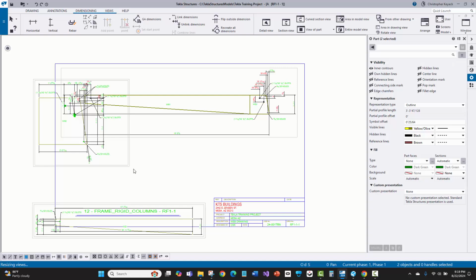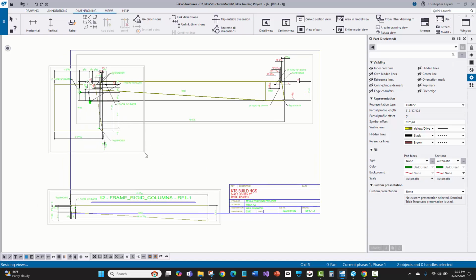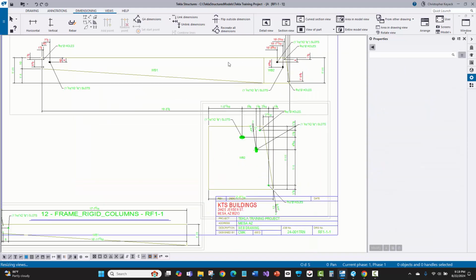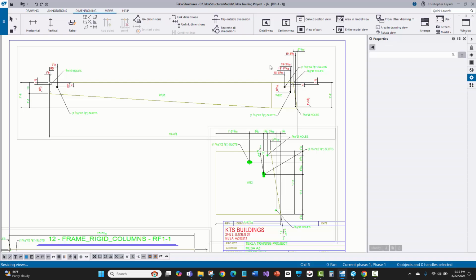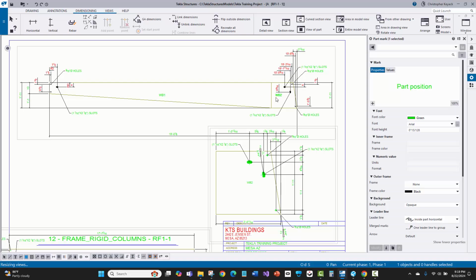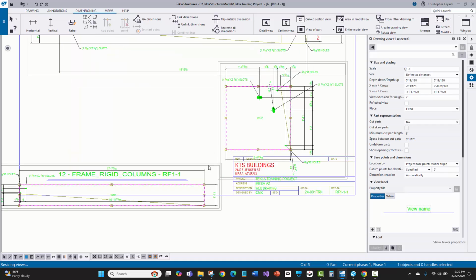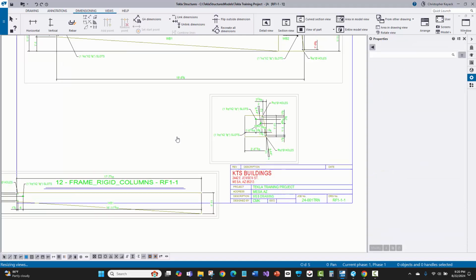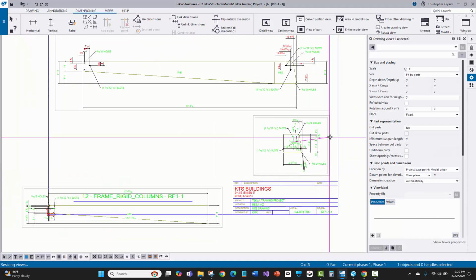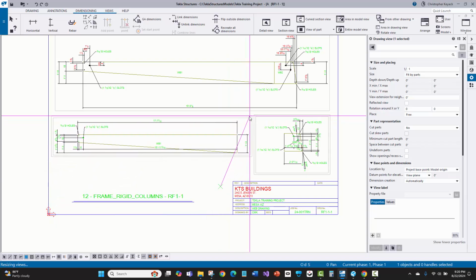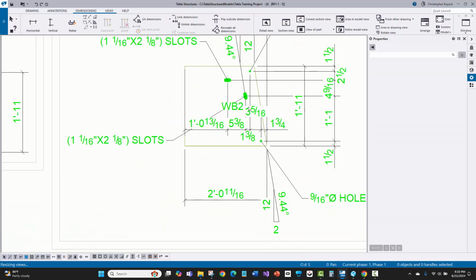And that adds a couple of views here of just the individual plates. It's got a lot more dimensions, including the bevels. So that's why I was saying that maybe I was adding too many dimensions up here on the top, which is primarily for the purpose of showing the orientation and which web goes where on the assembly. Now, on these inside views, I'm going to click on these, come up to the contextual toolbar, and change the scale to, say, 24. That's a little bit smaller scale than what's shown in the main view, so that I can fit these side by side, which gets pretty close to what you would see on a traditional web drawing coming from MBS.